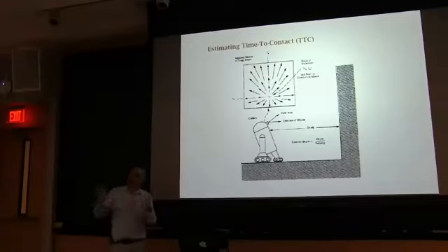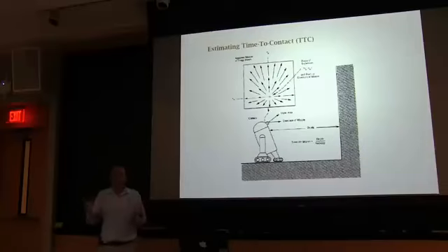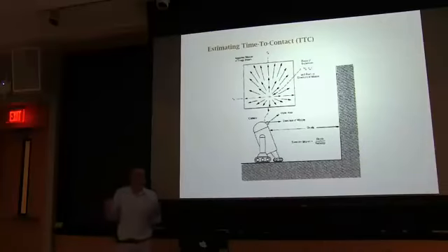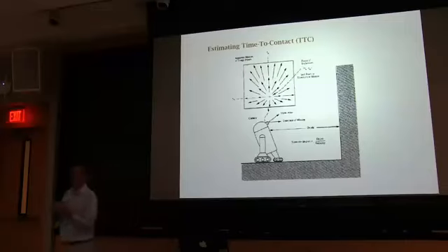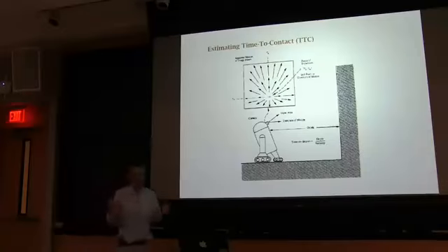Well, you can just divide the number of columns and the number of rows by 2, but that's totally arbitrary. What you really want to know is if you put the axis through the lens, where does it hit the image plane? Of course, the manufacturer typically tries to make that be exactly the center of your image sensor, but it's always going to be a little bit off.